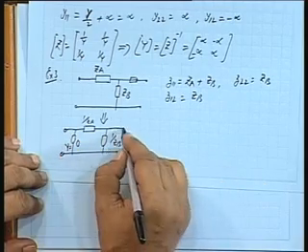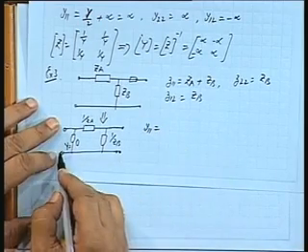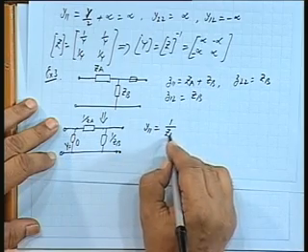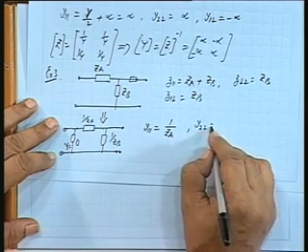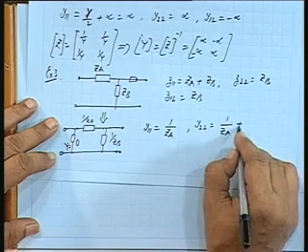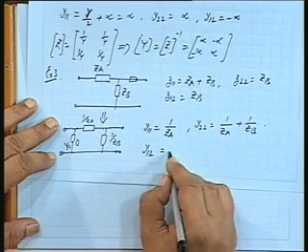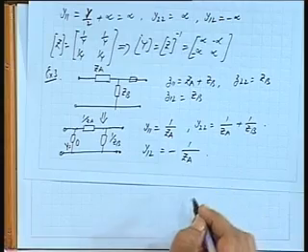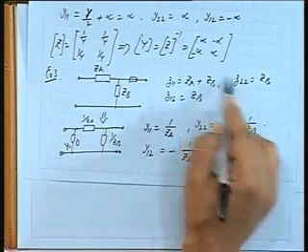Now, you calculate the Y parameters. What will be Y11? Y11 is this plus this, so 1 by ZA. Okay. Y22 is 1 by ZA plus 1 by ZB. And Y12 is minus 1 by ZA. Is that all right? You will find if I take the inverse of this matrix, I will get this ZB. Elements of this Z matrix will be like this.